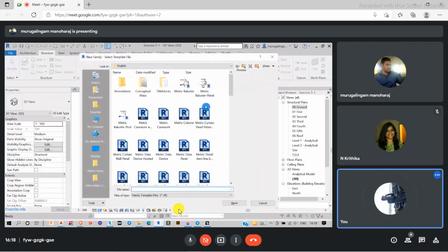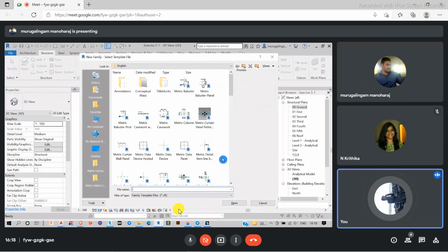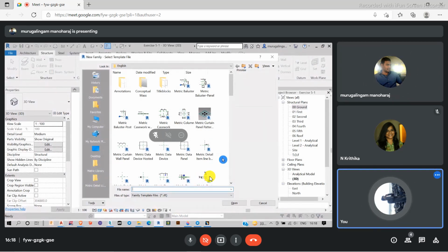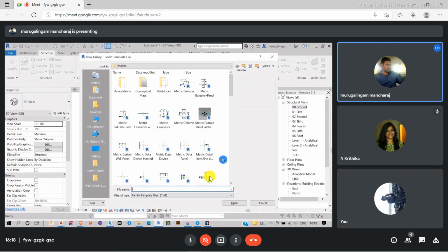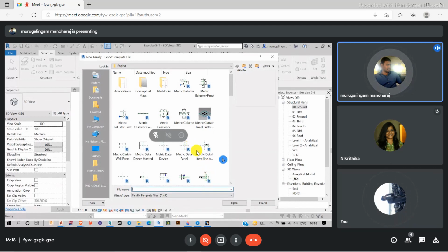In Revit architecture, what kind of families do you generally use for creating elements? Metric, sir. Apart from that, there will be a lot of categories, right? Yes, sir. It depends upon the component. Some people do it with generic. If I don't need an estimate, I can go on with generic because it is not going to calculate. It doesn't indicate what kind of material it is, so I can easily go on with generic.